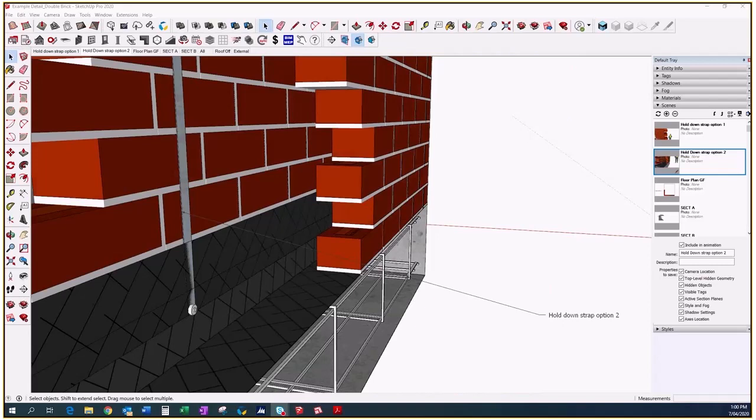3D details won't automatically update though. So if you've got a 3D detail of your project and you brought in a double brick vignette, and you change it to, for example, a concrete wall, you're going to have to dump that 3D vignette and replace it or redraw it if you don't have it. Conversely, say you have a double brick vignette and you change the cavity, and your 3D detail has the old cavity size, you'll need to manually adjust it to the new cavity. Very, very easy to do though.